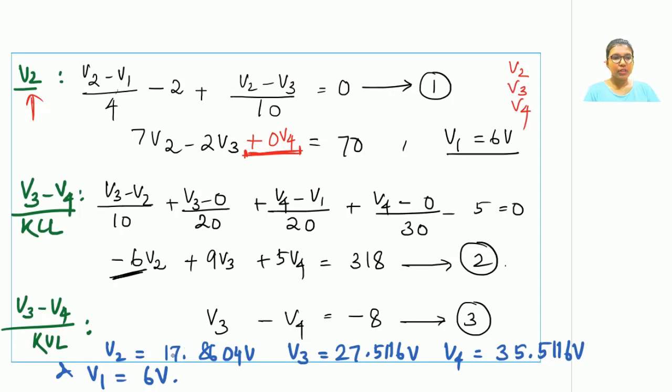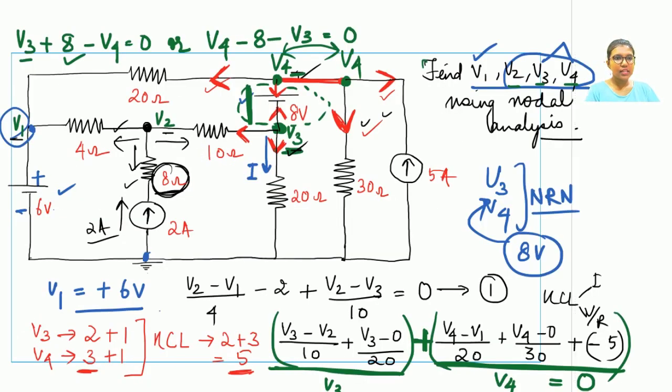So with this, we have solved all the values of the node voltages. Now let us go back to the question. Now in this question, one can see there is this current I mentioned over here in the downward direction. So this question asks us to figure out the value of I in the downward direction. This current I is flowing through the branch which is connected to node V3. And when V3 is considered to be at a higher potential, the current is made to flow in the outward direction. So the direction of I asked in this question is in the positive direction as of our analysis.